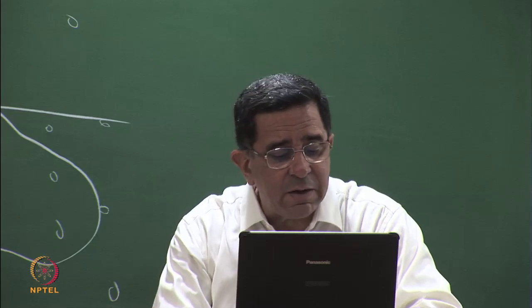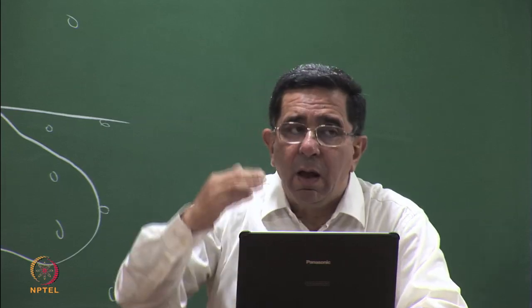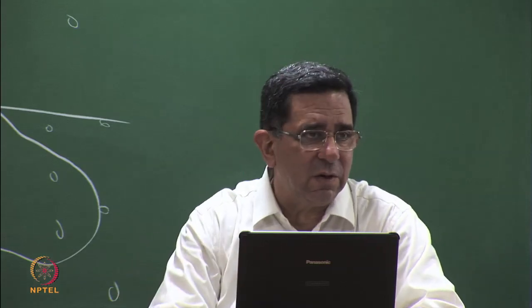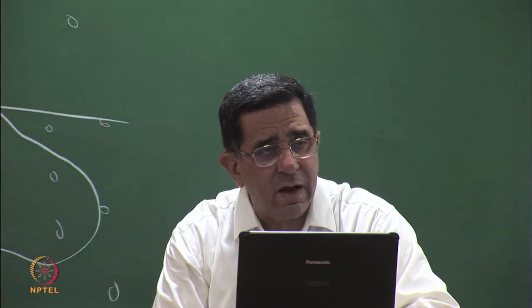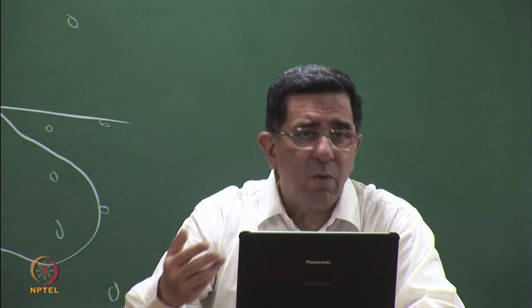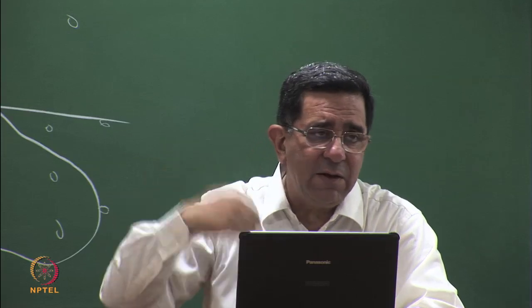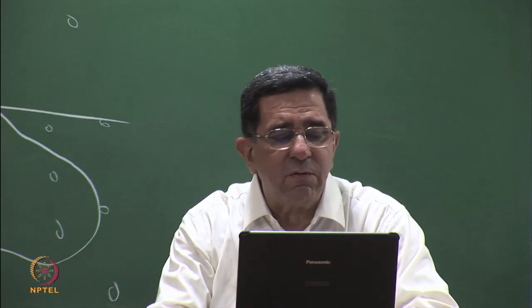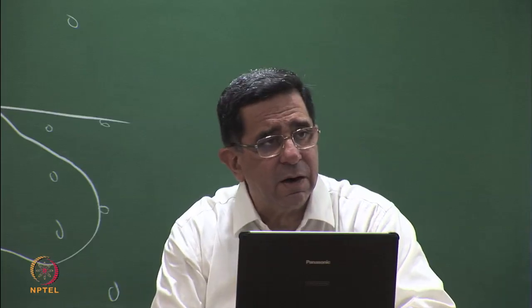And because it's a contaminated site, monitoring will be done right from the very beginning, all through remedial action, and post-remedial action as well. That means this is going to be a totally instrumented site where data, what were the levels before, what are the levels 1 month after, 1 year after, 5 years after, 10 years after, what are the contaminant levels will have to be monitored. So this is the full planning and implementation methodology. And do remember that no single solution is there which I can hand out over to you and say this can be adopted.